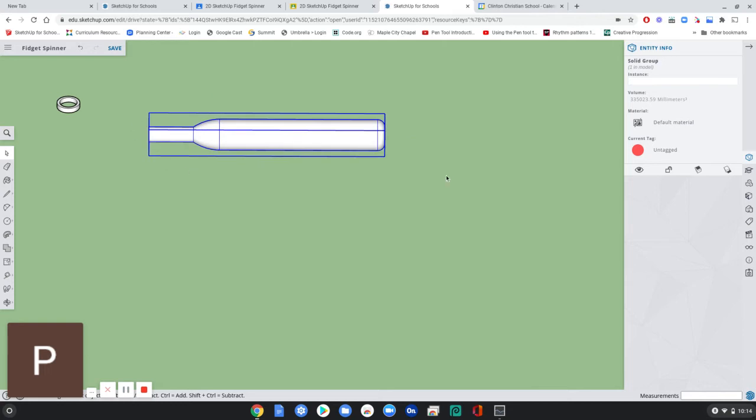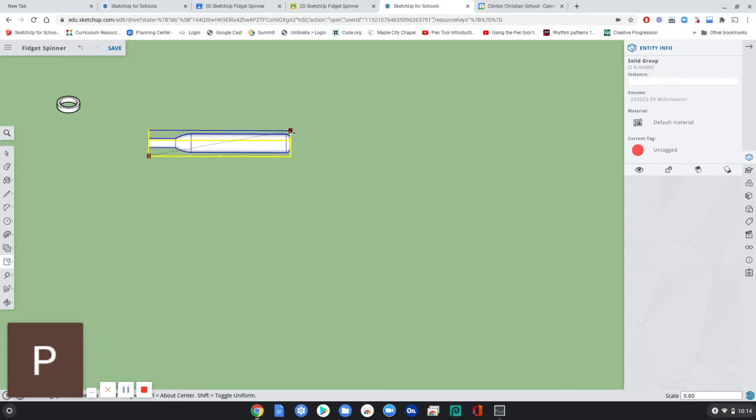It's a good day. So now I'm going to scale this back down to size. So I could use the scale tool. Grab one of the corners so I scale uniformly. And then I want to do 0.1 because that's 1/10 of what it is now. 0.1. Enter.